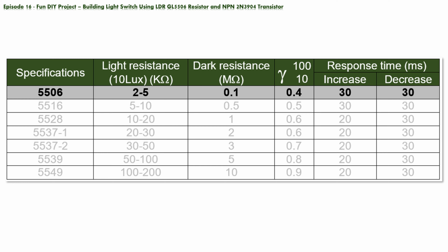This is important information, in case that we want to use LDR as some sort of counter, to count changes in light intensity. In the perfect scenario, we could observe and count 3 different changes in light level, from dark to light and back, in 1 second. To summarize, the most important thing for us is that, when there is some light, the resistance of our LDR is between 2 and 5 kiloohms, and when there is no light, the resistance is 100 kiloohms.